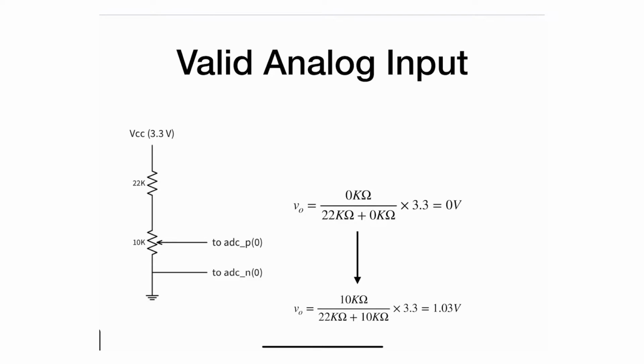So to guarantee the specification, we have to make sure that the input to the ADC is just between 0 and 1, and the way we can do it is using a very simple voltage divider. So this voltage divider does the following. The VCC is the voltage available on the board in some of the pins on the XADC that we're going to be using. It gives us about 3.3 volts, and we have a ground of 0.